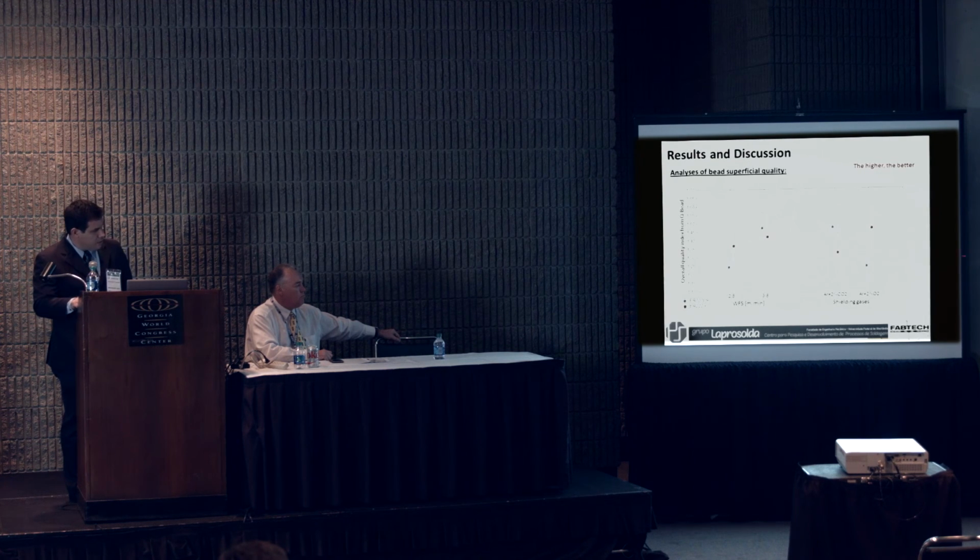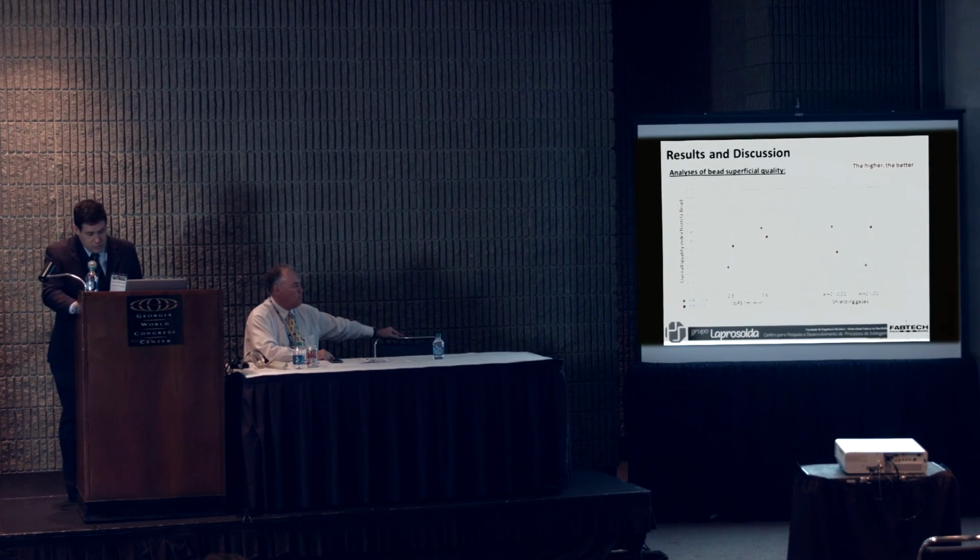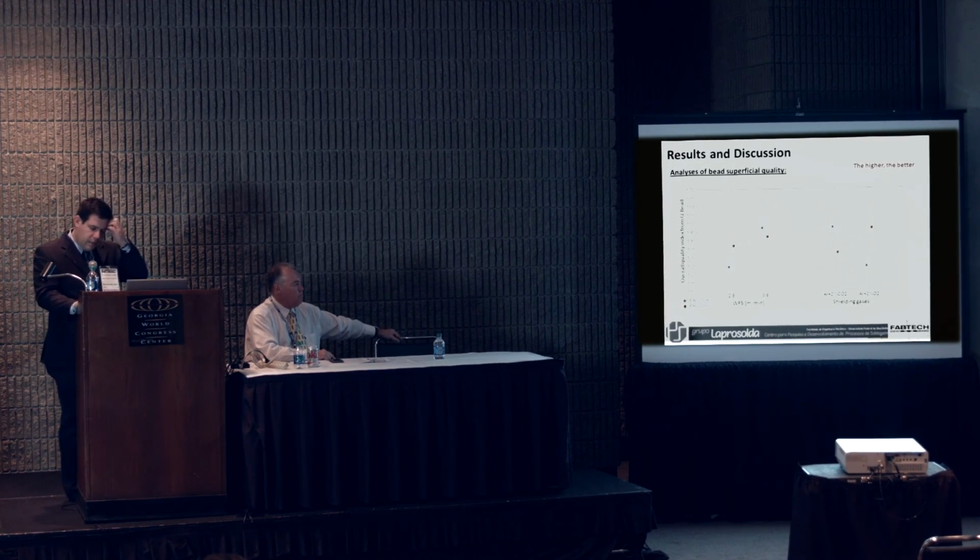So perhaps for austenitic we are in agreement with the literature, but for duplex stainless steel, no, because the best feature of the weld bead was achieved by using argon with 2% O2. We still have to analyze the metallurgy here, if everything changed, but it's tricky because with pure austenitic you change the surface tension, you change a lot of things. There is still a lot of work to carry out to clear up all those aspects.